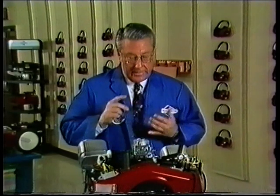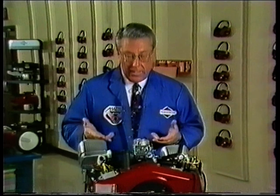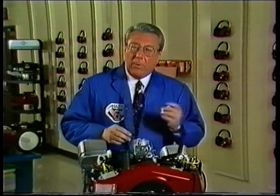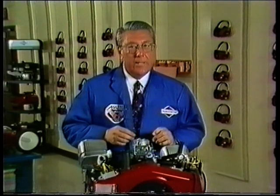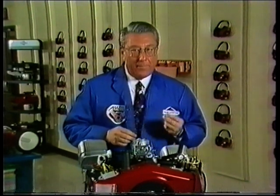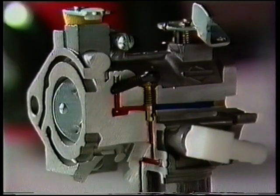We can assume that the air bleeds, main jet, and the main fuel supply are all okay, since performance under load is acceptable. When we also consider that the reservoir of fuel feeding to the engine during idle and top no load is pulled through this common circuit, it becomes evident that the idle transitional circuit must be the source of our problem. What about the opposite problem?